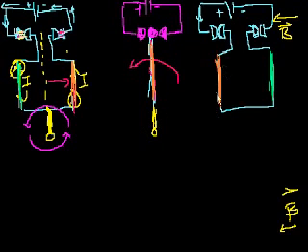So what happens here? Now this side, instead of being connected to this lead, is now connected to this lead. And this green side is now connected to this lead. So something interesting happens. Now the current on the left side is still flowing down, right? And the current on the right side is still flowing up. So we're back to this configuration, except that this contraption has flipped over. The brown side is now on the left, and the green side is now on the right. And what that allows is that those net torques are still going in that same rotational direction.